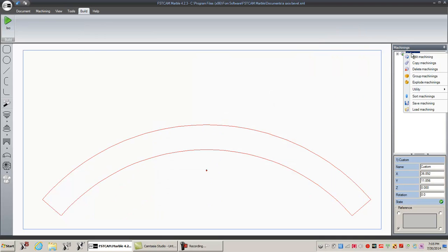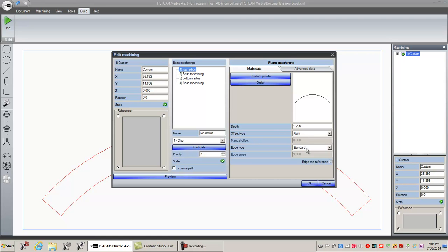So let's go back there. Okay, top radius. We're leaving this standard, it's 90 degrees. And the scrap is going to have the bevel on it from the blade. But when you're cutting the inside radius, you're going to have to select user angle, click here, right click, accept the prompt for suggested angle. The A-axis will tilt on the appropriate angle.